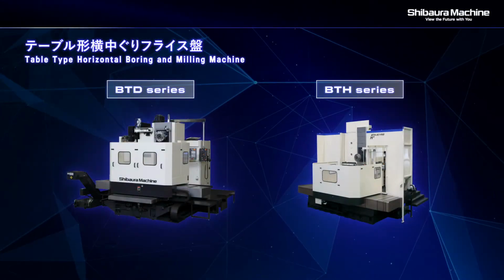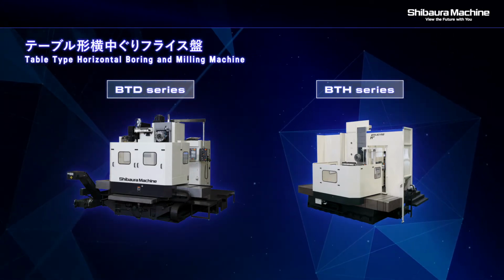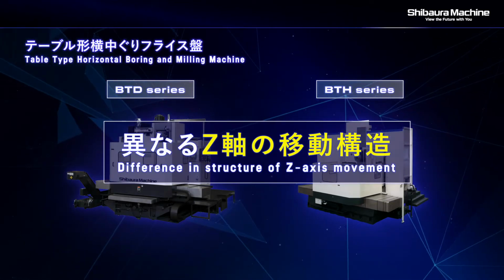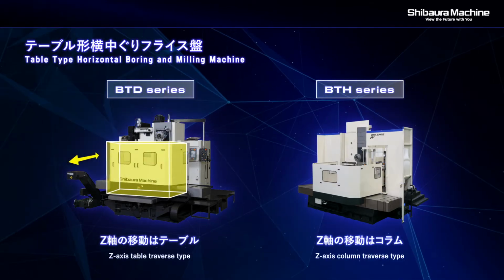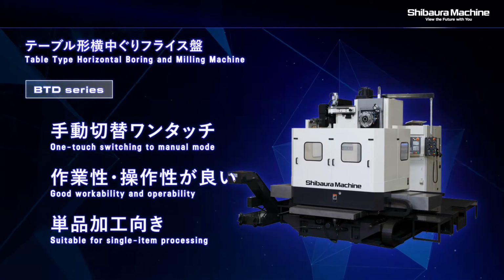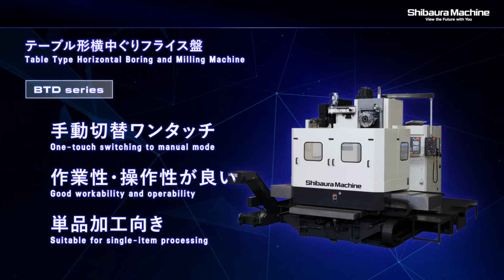From our wide lineup, we would like to introduce the Table-Type Horizontal Boring and Milling Machine Series, BTD and BTH. The major difference between the two models is the Z-axis movement structure. BTD is table traverse type. BTH is column traverse type. BTD has good workability and operability and is suitable for single-item processing with frequent setup changes and positioning.